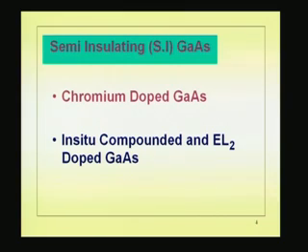Another thing that they have done recently is, do not let the silicon come in. Somehow manage to grow the crystal by starting with high purity gallium and high purity arsenic, then make a compound, that is an in situ compound, and then grow. That turns out to be p-type, due to some contaminants like carbon, contaminants like boron coming in. So, you have no choice.